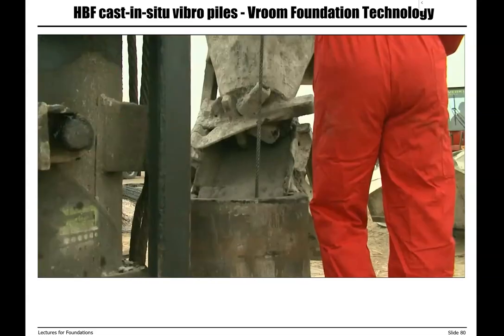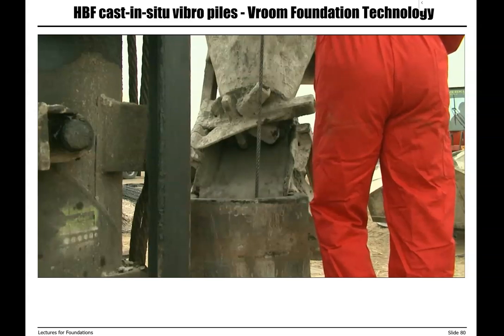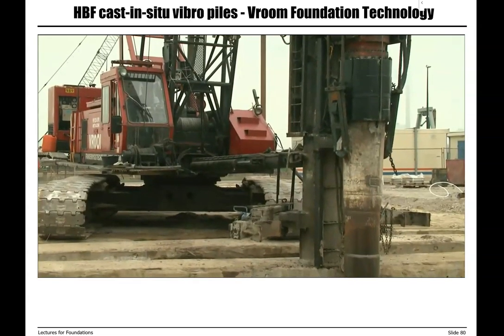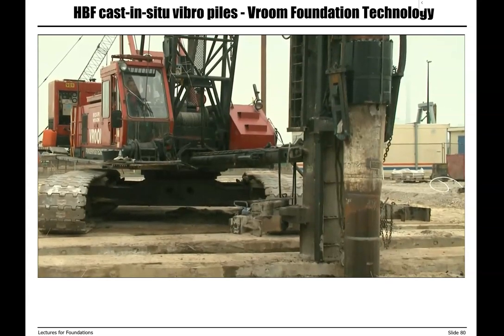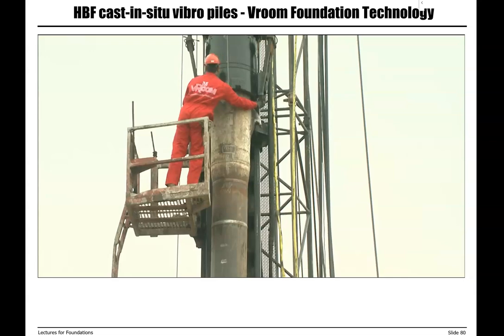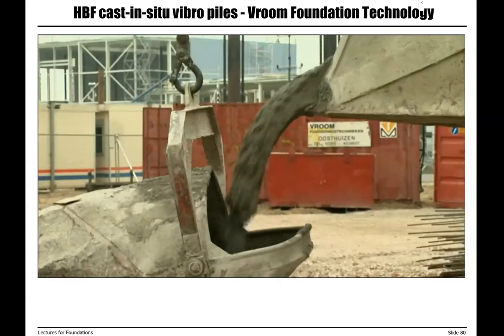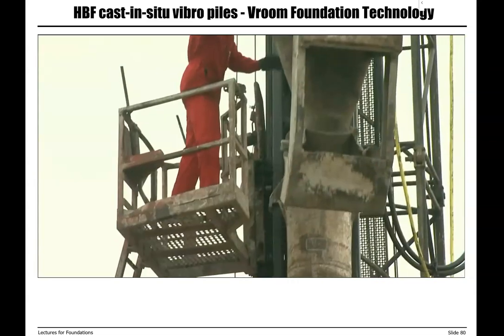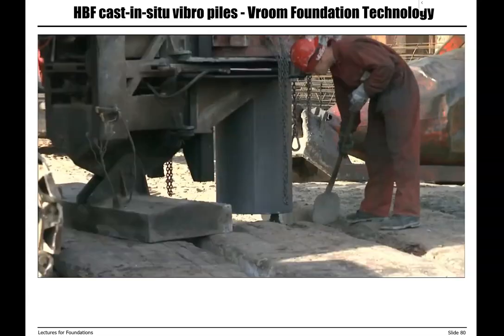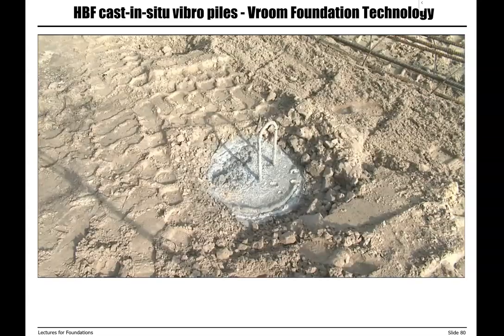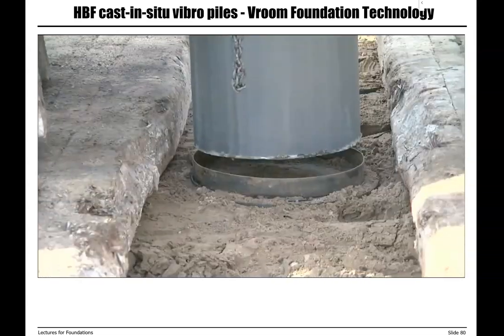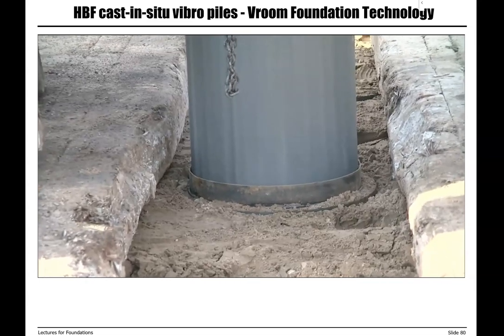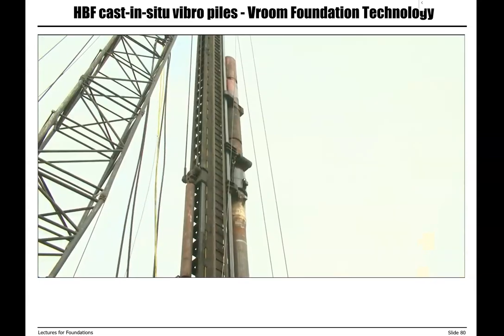A concrete pouring silo is used to fill the concrete into the casing, after which the driving hammer is again connected to the casing. When the piling rig withdraws the casing, the detachable base cover remains behind and shapes the vibra pile in the soil. Vibra piles can always be made to the right depth. If required, a pile can be finished directly at working length. For each subsequent pile, the same casing is positioned over a new shoe and pile driven into the soil.